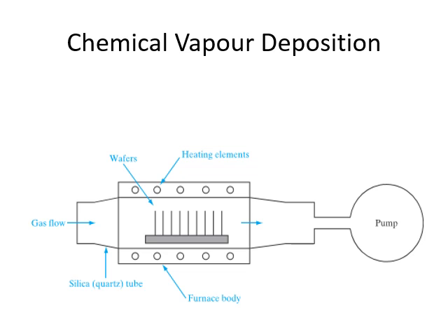Then we saw chemical vapor deposition. In chemical vapor deposition, the vapors are inside the electric furnace, and there we saw two types: low pressure chemical vapor deposition, and plasma enhanced chemical vapor deposition. This diagram is telling about low pressure chemical vapor deposition.